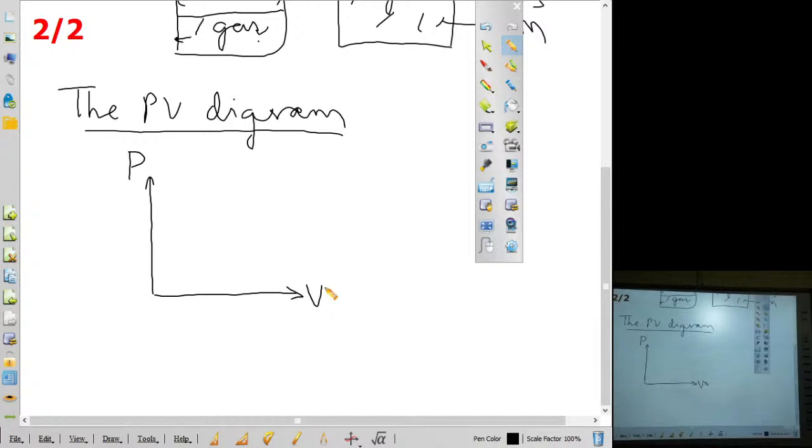It is that just like that we have taken pressure as the height and volume as the length. There is a reason for it. We will study all that also. These reasons we will see it later on. And any one point you take here, let us say it is the first point, so point 1. That point is called state point of the gas. You know why it is called the state point? Because a single point in this diagram will tell us what is the state of the gas. If you see what is the height at point 1, it will be equal to the pressure. Height is equal to, you can see here, pressure is given by the height.